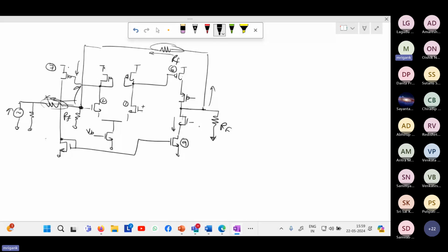Right now, just at a high level, you understand that we are using an RF as a shunt feedback, and for opening the loop, we will have to basically consider the loading effect by opening RF from this point to ground and input side also RF to ground. And in this case, gm·ro² is a large impedance and RF is going to be relatively small. As a result, it can affect the gain.